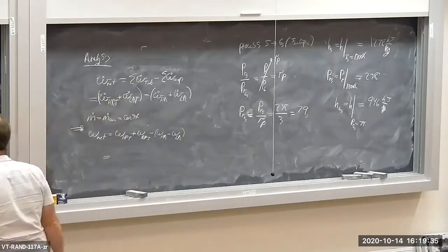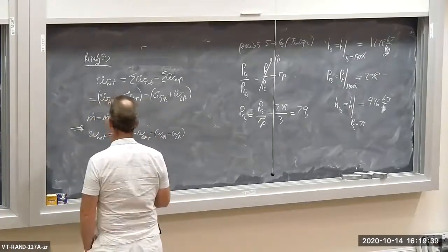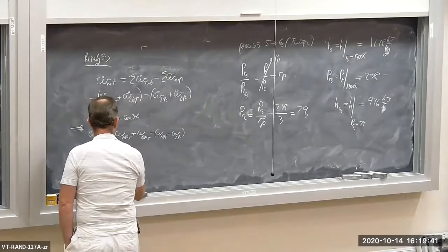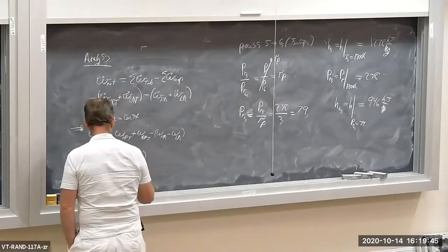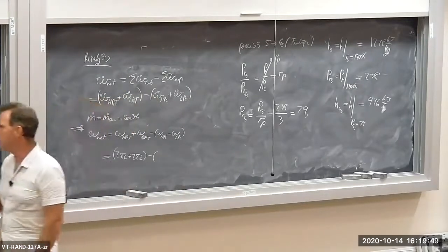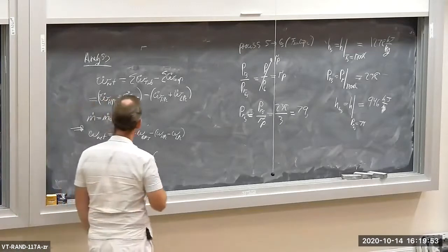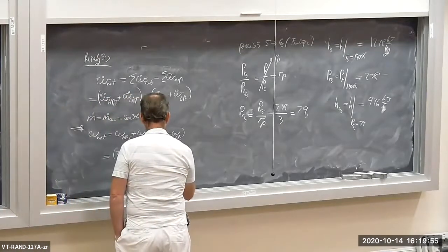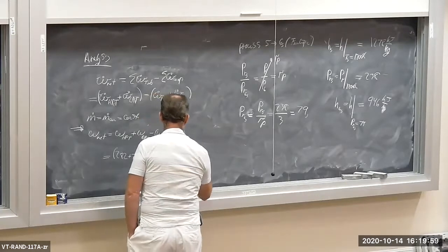The LPT and the HPT both produce 280 kilojoules per kilogram. And both of the compressors consume 139 because they have the same efficiency, the same inlet conditions, and the same pressure ratios.